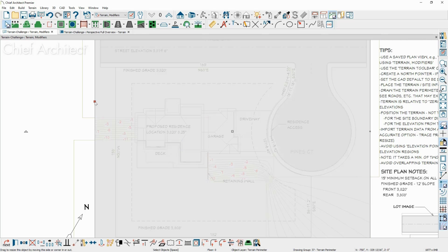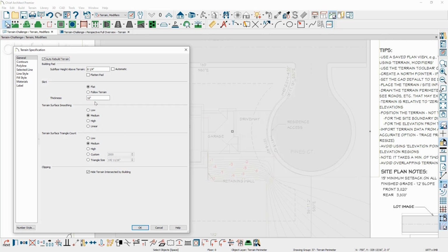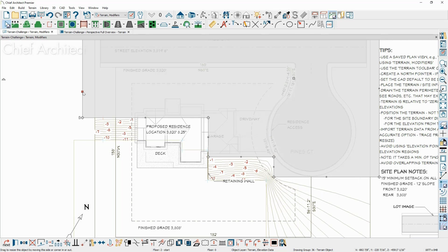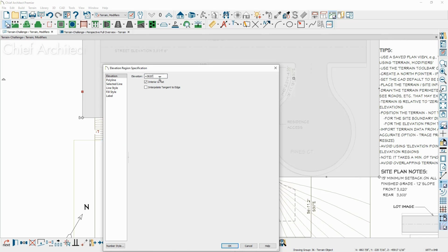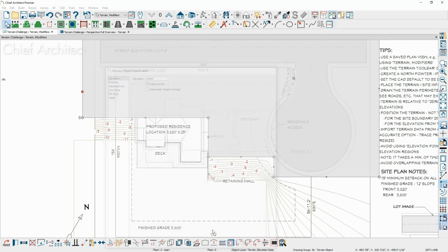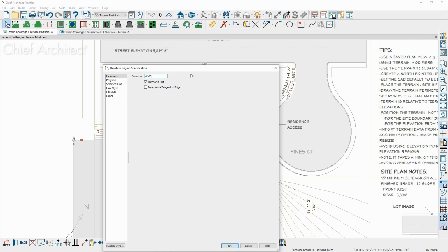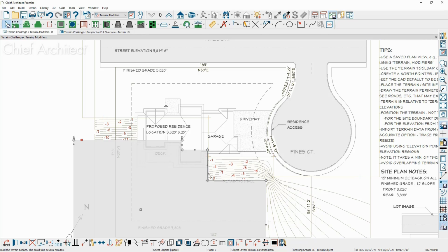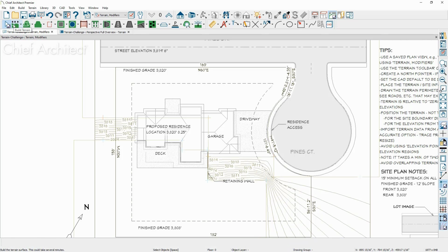Here's what I'm going to do. I'm going to open up the terrain perimeter, and I'm going to come into where our subfloor height is, and I'm going to say plus 3820 in feet. Let's go ahead and copy that number because I'm going to have to use this 2 more times. Plus 3820 feet. And then I'm going to do the exact same operation on the terrain regions we created, plus 3820. That will resolve in inches, and then we'll do the same thing. Plus 3820, rebuild the terrain, and now you can see those are displaying in sea level numbers.